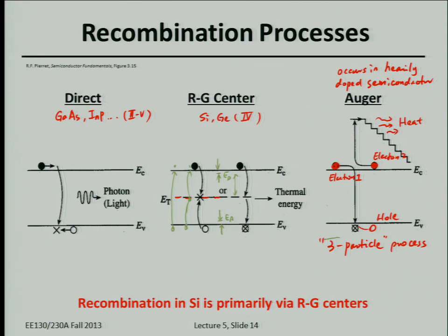For higher performance semiconductor devices in general, you don't want a lot of these trap states present. Things like trace metals, trace amounts of gold or any other metallic contaminant, are not desired. But the key thing to remember here is that doping does not affect the recombination and generation lifetime because the dopant levels are not anywhere near mid-gap. Although dopant concentrations degrade mobility because they're ionized impurities, they're not going to affect the minority carrier lifetime. Okay. Any other questions?